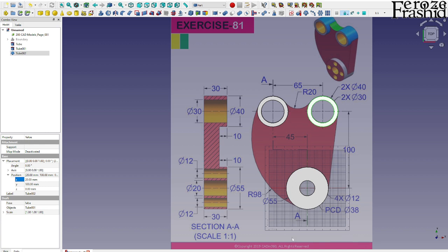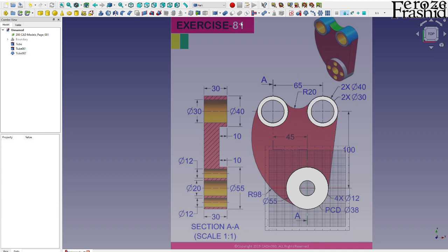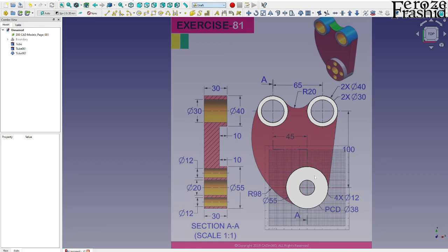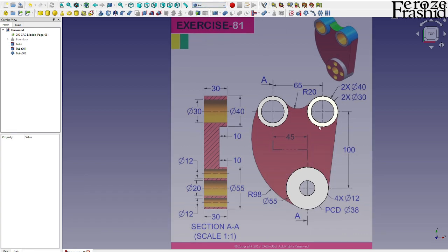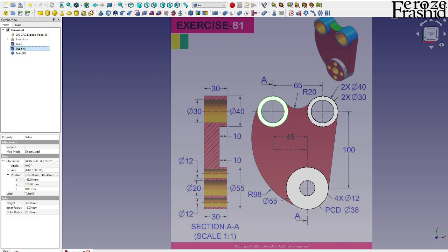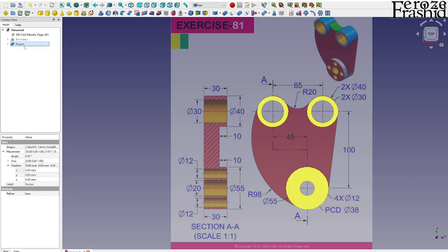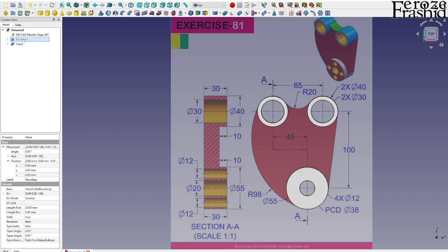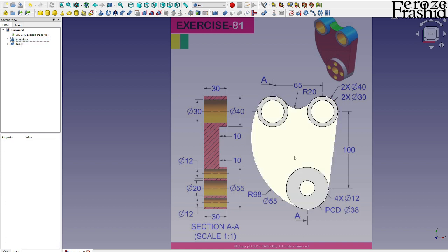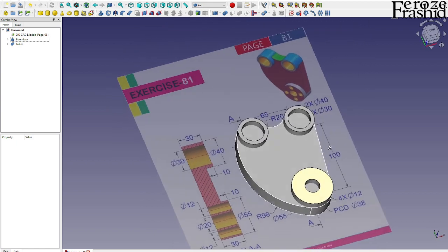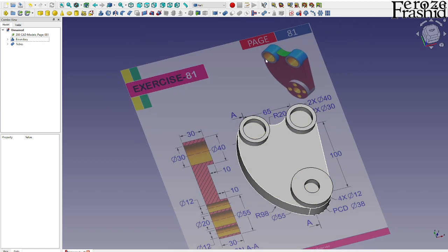Okay, let's take this mesh away. Yeah, we don't need the mesh. Alright, so we have 3 tubes, and I want to make them one body. So let's make that union, and I'll say tubes. Let's bring back our boundary, and now I want to use the connect tool to have this the way it is there. So make all those holes on the inside.